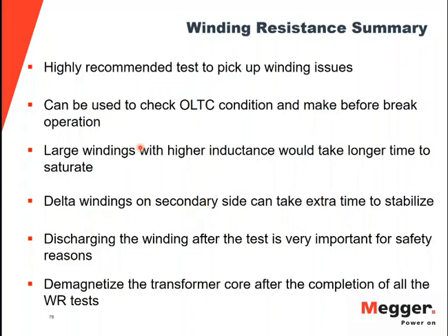And the last thing is that you should demagnetize the transformer once you have completed the winding resistance test, so that way there is no residual flux in the transformer.